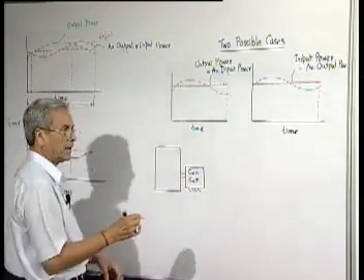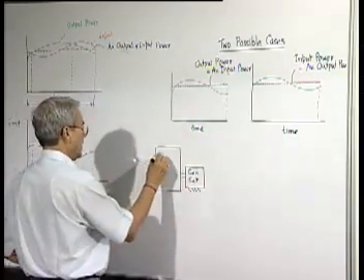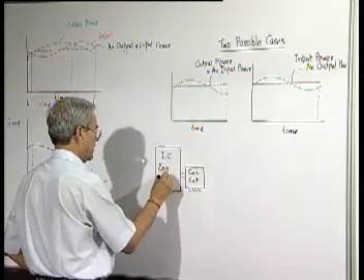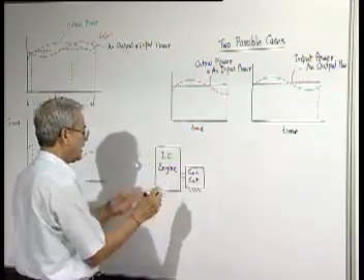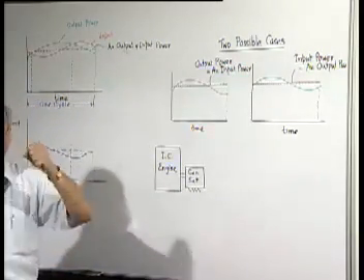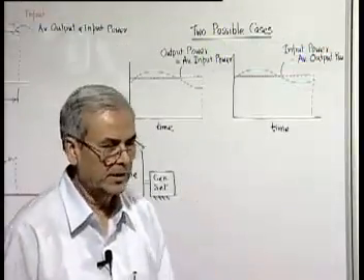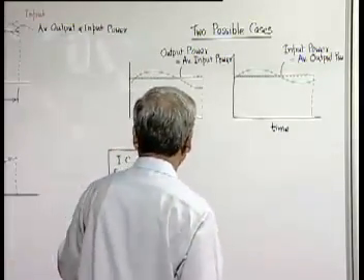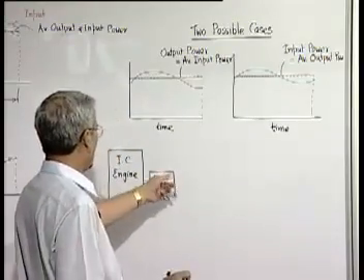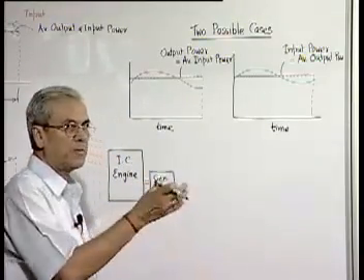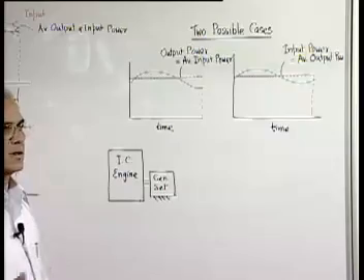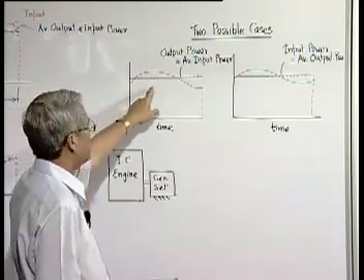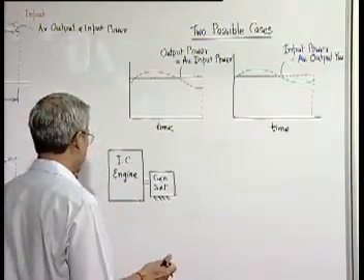Producing electric current, and the load is constant, and this is the IC engine, say a diesel engine. Here you will find the mechanical torque produced on the crankshaft is fluctuating, that is, the input power is fluctuating, but the load or the resisting load produced by the generator is constant, as our electric load is constant. So this will represent a situation like this.